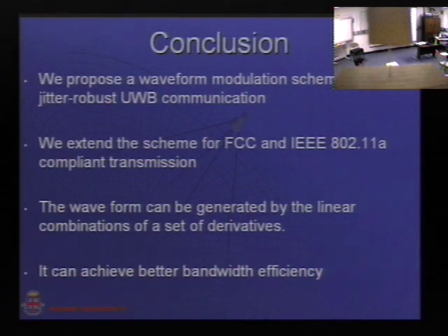If you think about the first pulse, the difference between the amplitude of the first pulse and the 7th order pulse will be like 1,000, even more than that. So how do you realize an amplifier like that? You can accurately realize a dynamic range of maybe 10 to the 4th order. That is realistic mathematically, or in MATLAB, but in reality, I don't think you can realize that.